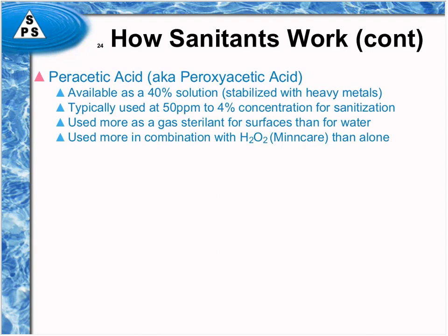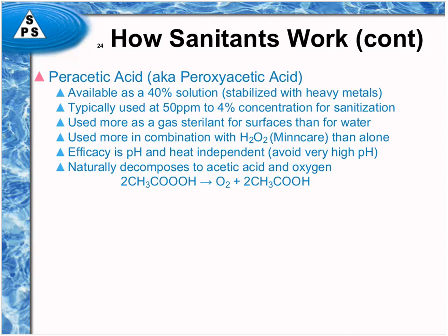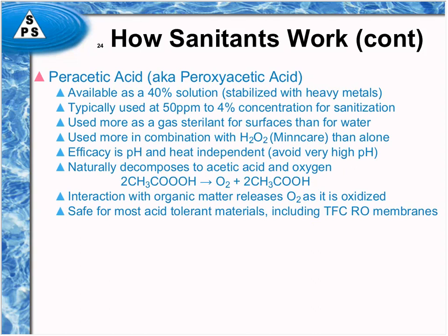It's used often in water systems when it's combined with hydrogen peroxide in these proprietary mixes like MinCare and Spore Cleanse than it is when it's used alone. Its efficacy is pH and heat independent, but avoid very high pHs because they actually do degrade it. It does decompose to acetic acid and oxygen, so that's why the smell of peracetic acid is a little bit like vinegar, because what you're smelling is a decomposition product, which is the acetic acid. Interaction with organic matter does release oxygen as it works.